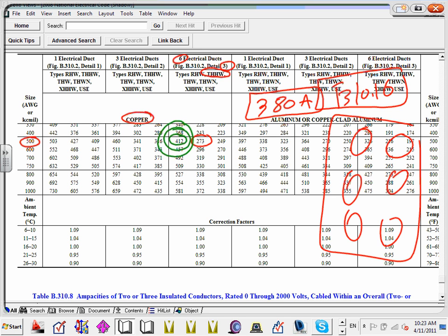Or if this conductor is going to be loaded and the one next to it's not loaded, you can carry 416. So a lot of people say, okay, I have all these 6 ducts. What's the likelihood that they're going to be carrying really 4,000 amp in real life? Most of it is just addition and padding because of safety. In reality, when everything is up and running, you're lucky if the 4,000 amp cables are carrying 60% of their load.